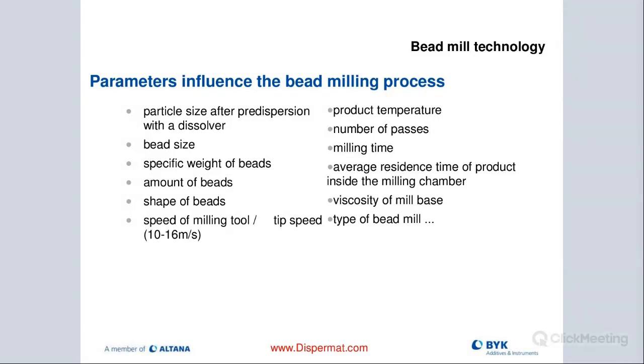The shape of the beads is also very important. So we always recommend that you screen the beads, not after every trial, but once every week or 2 weeks, depending on how often you use those beads, to ensure that you get rid of the fines and the broken up bead particles, if there are any, because that would lead you to uneven results. And if you try to be repeatable in your trials or your process, you always want to have good bead consistency. And again, this is always very important.